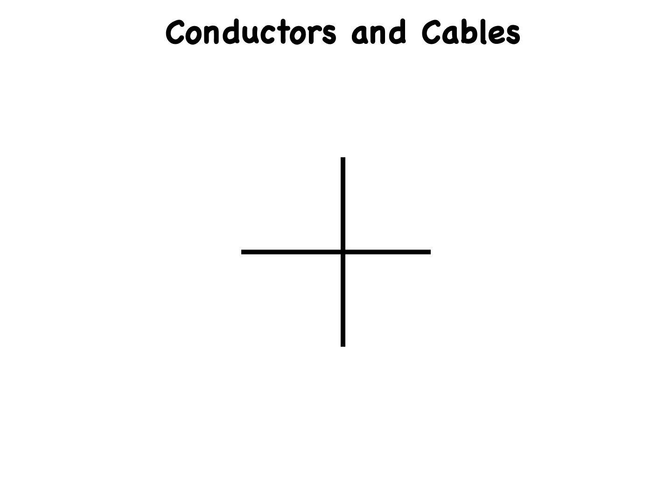This diagram geometry does not imply that when you build the circuit, the conductors must physically cross over each other at that exact place. It simply means that in order to make the schematic drawing, you have to draw one conductor across another to reach various circuit points without introducing a whole lot of confusion and clutter, or resorting to 3 dimensions to make your drawing. A real-world circuit exists in 3-dimensional space, but when you want to diagram it, you must do it on a 2-dimensional surface. To carry off that feat, you must learn a few tricks to make sure that your readers see things right.